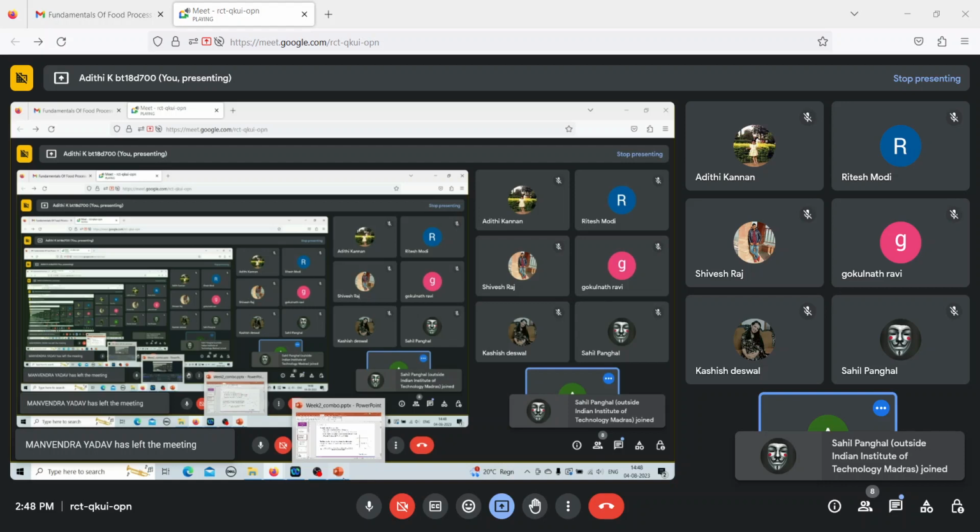Basically, to sum up, the Deborah's number represents the ratio of the duration of the fluid memory to the duration of the deformation process and is used as a measure of viscoelasticity. So if Deborah's number is less than 1, that is, if the relaxation time of the liquid is less than the characteristic deformation time, the fluid appears to be more viscous than elastic.